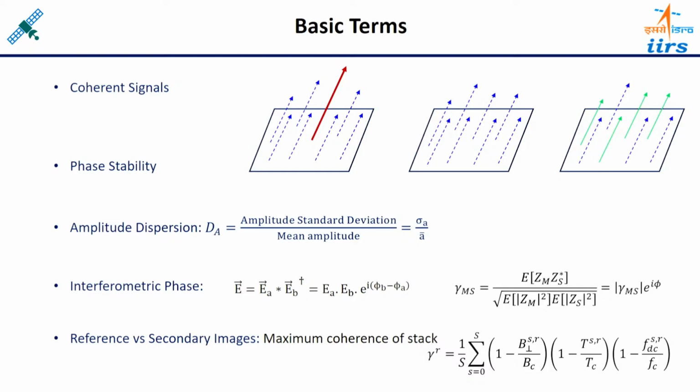This shows that in this resolution cell many types of scatterers are there, or you can say two categories of scatterers are there. One scatterer is responding with backscatter energy very strongly. The backscatter information corresponding to this red response is very high, and the backscatter from the other targets represented by the blue colors is not that high, or you can say a moderate level of backscattering is happening from the other types of targets.